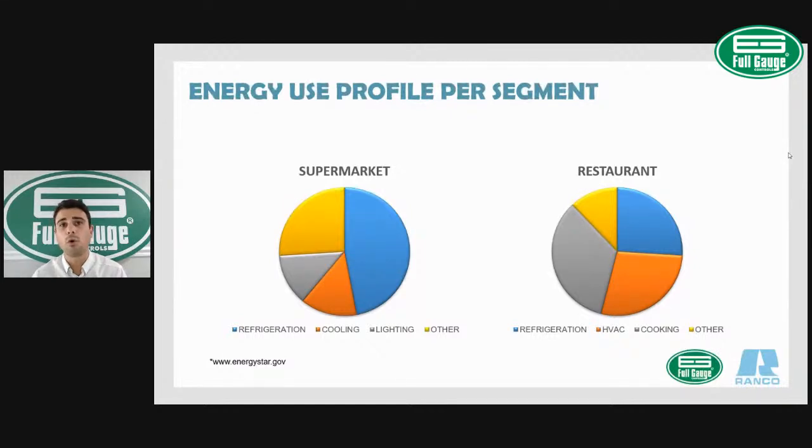And not only because of the resistance that is activated to defrost the ice, but also during the ice formation process, in which the evaporator coil loses efficiency. So there you have energy wasting, because your coil is actually forming ice, and that ice is preventing heat transfer.